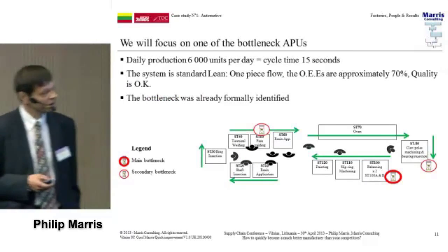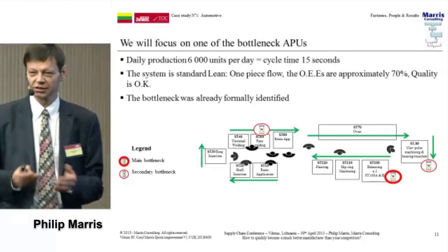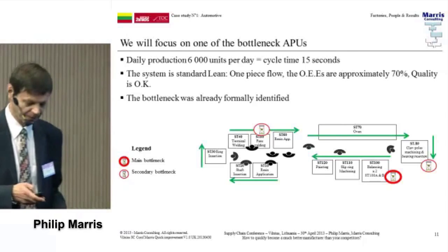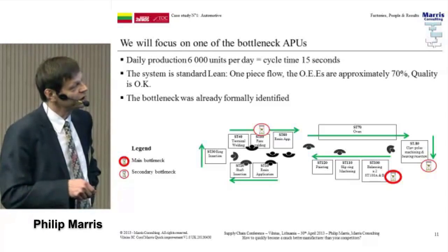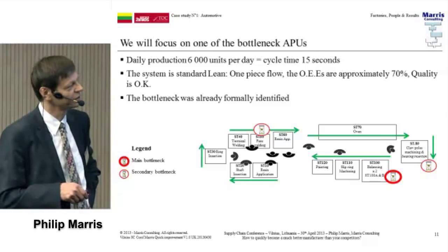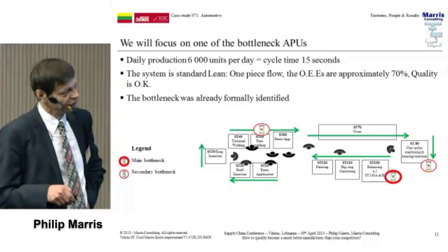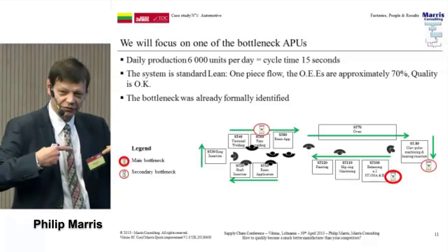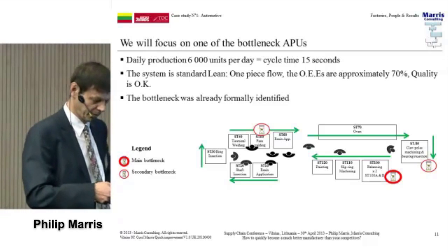So it's a U cell producing the rotor of the alternator. It's about this size, about 3 kilos. The product comes in here and goes around what would be called a U cell. Comes out here. The various parts are added little by little. It goes through an operation in an oven here. It's nearly finished coming out here. Here they have to balance it to make sure that when it spins very fast, there's no vibration. And then they finish it and come out here.